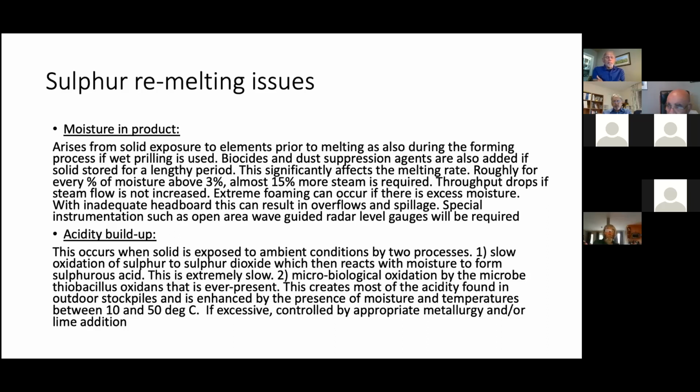The other problem with moisture is you can have foaming. When you start melting, you have extreme foaming, and if you do not design with enough headroom above, that foaming can spill over your melting process.